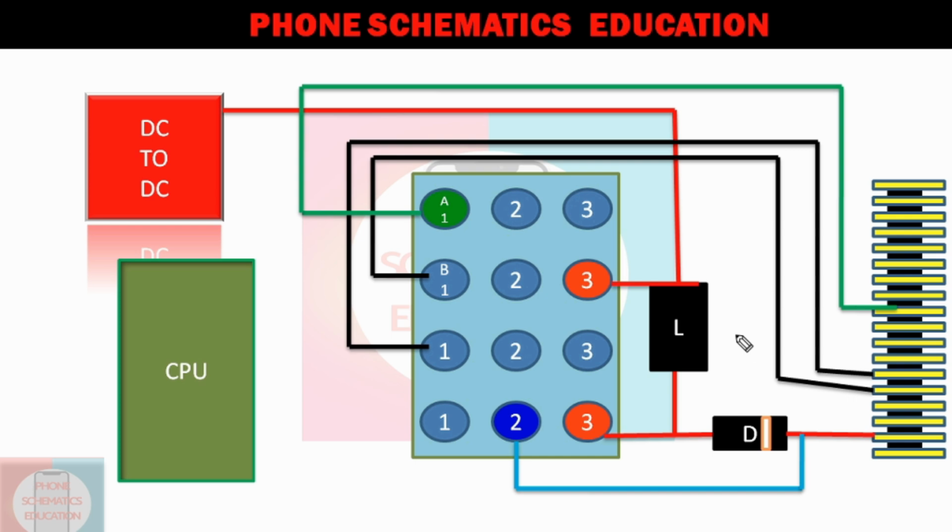So I also have a trick, one click, or you can say a shortcut trick, through which you can verify whether the problem is in your light IC or light section, or your graphics section. I will tell you later. Now you must have understood what these three lines do. CABC is the brightness controller, cathode is a negative, and anode is a positive. How do these three lines work, connecting to the IC?